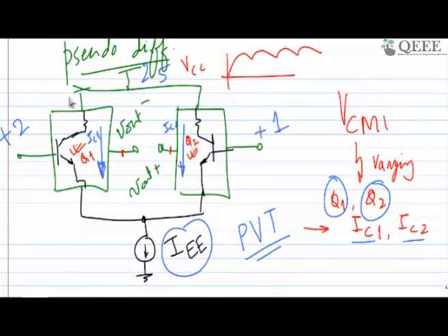So this side plus 1 volt, this side plus 2 volt, this side plus 2.5 volt, means IC1 carries all the current, and IC2, as IC1 has eaten up all the current, cannot provide any current because it has to be 0, because the total of these two currents has to be equal to IE, and that's how KCL is being followed.